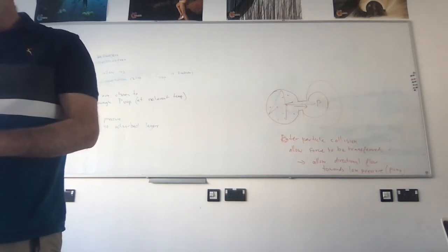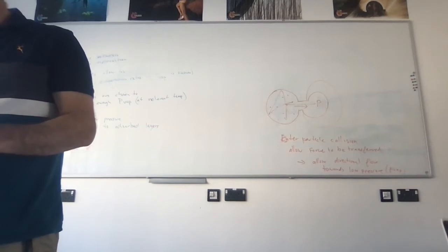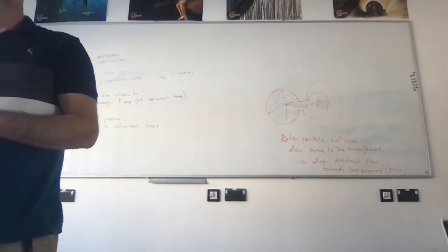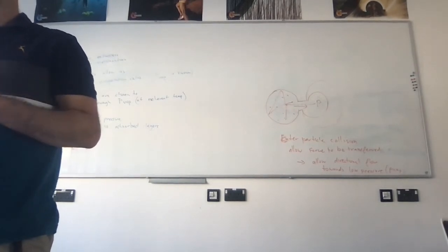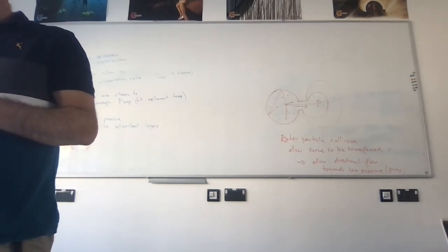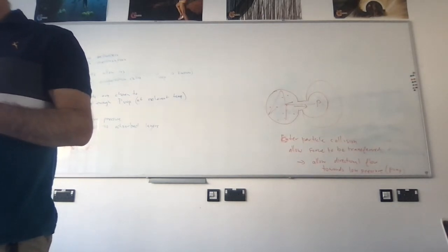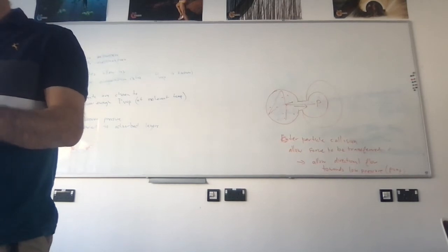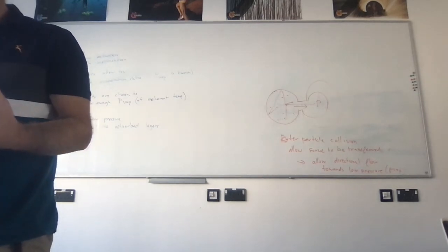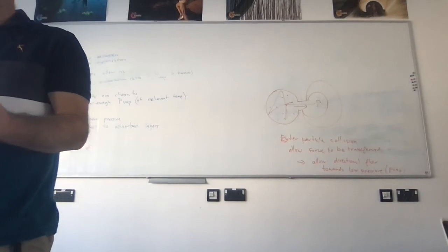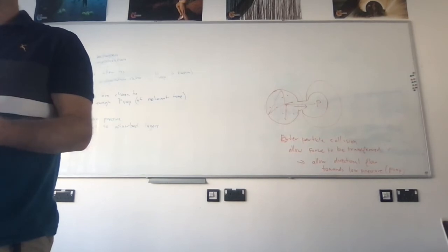By the way, one thing about these pumps is, what happens if you run them in reverse? Let's say you somehow replace the inlet and the outlet. We'll just get blocked because they won't be able to go the other way through the valve. They block gas running the wrong way. But let's say I somehow reverse their operational principle, so I put the valve which opens and reverse the directionality. That's called a compressor.